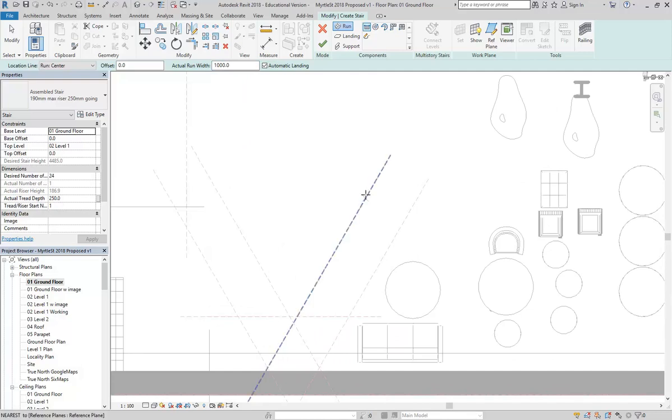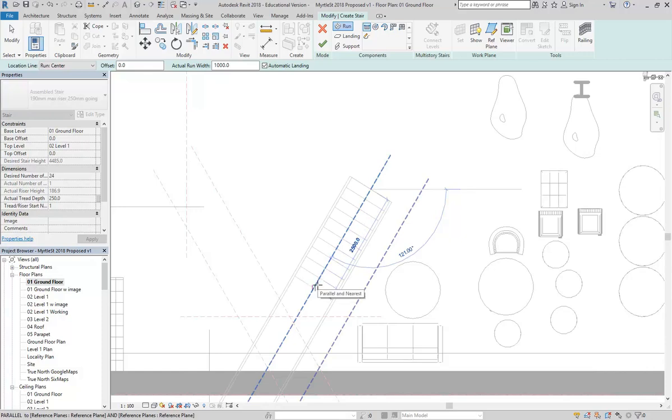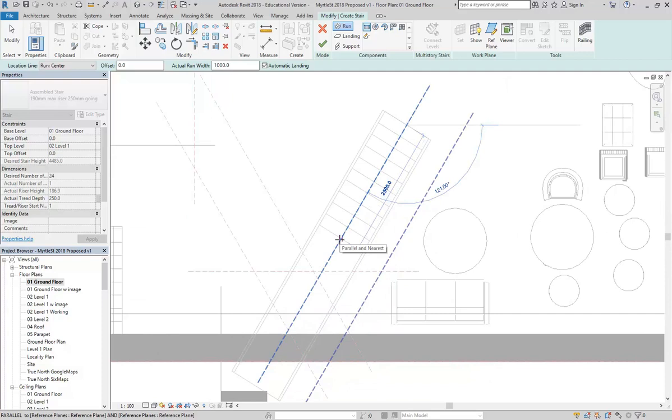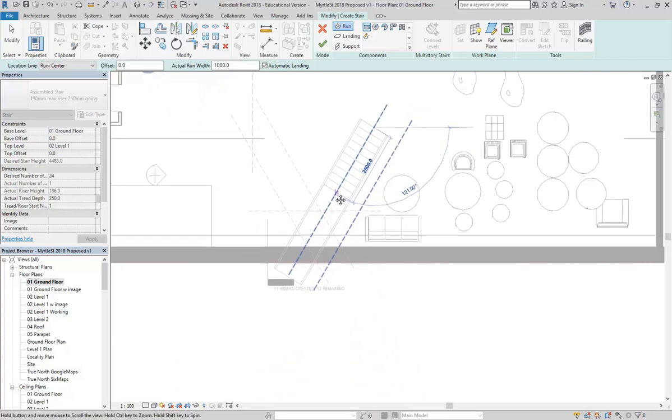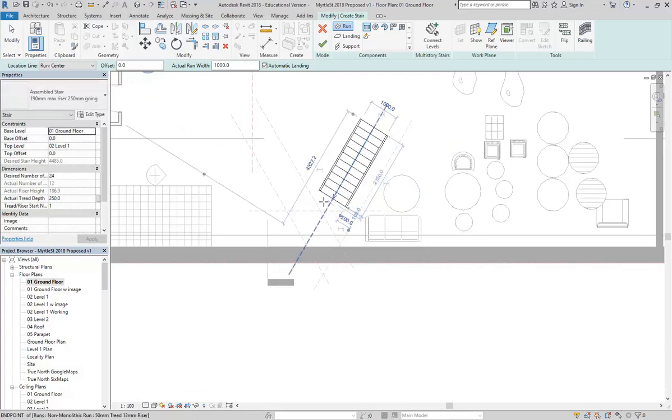So I'm just going to use a bit of a trick here. I'm going to trace over the reference plane to get the angle, and then do the number of steps I want. So I suppose I'll keep it even and do 12 on each side. I just can't see my text. It should give us a readout telling us how many I've done. Yeah, where is that? Oh, down the bottom, there it is, yep. Okay, so yeah, now it's got 12 created, 12 remaining.